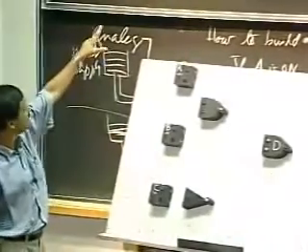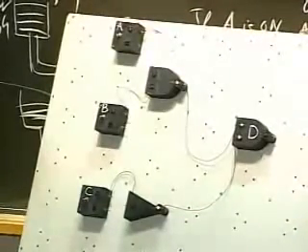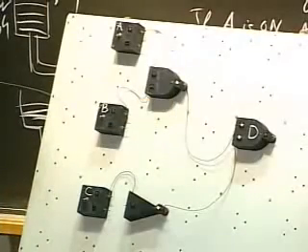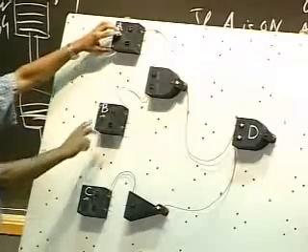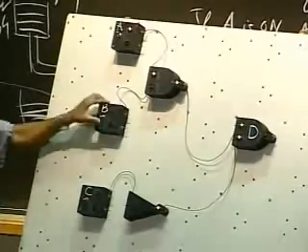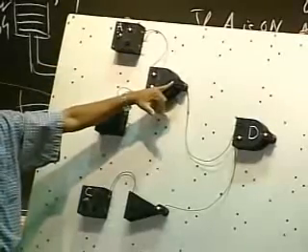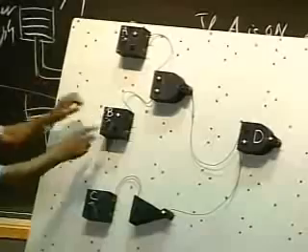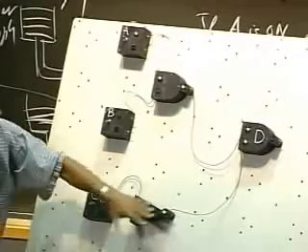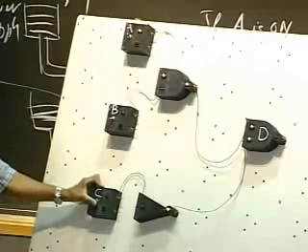So here's a little circuit that I showed you here. A, B, the NAND gate at the output, and the inverter. So this output is going to be 1 whenever either A or B is off. Okay, so the output is a 1 in this case when both A and B are off. I turn A to 1, output is still a 1. So the moment I turn both of these inputs to a 1, the output goes to 0. That's behavior of a NAND gate. If I switch any one of the inputs to a 0, the output should go to a 1. Similarly, for the inverter here, when the input's a 0, the output's a 1. And when I switch it, so should the output.